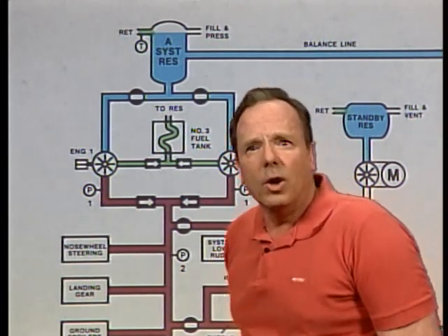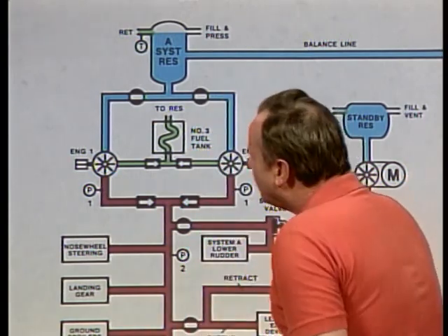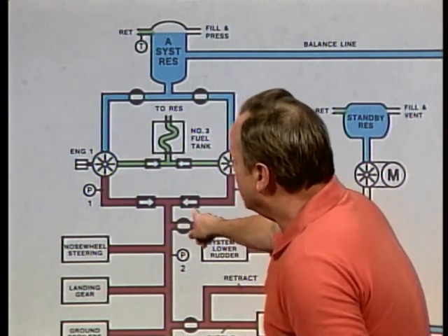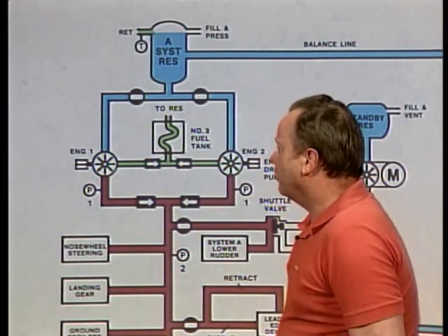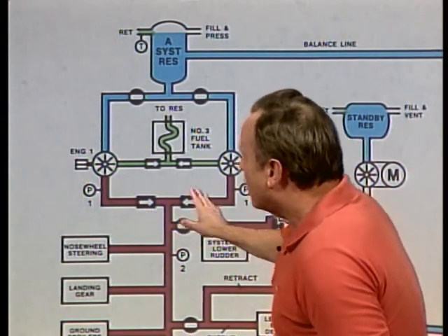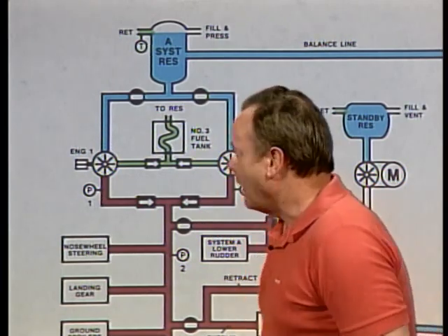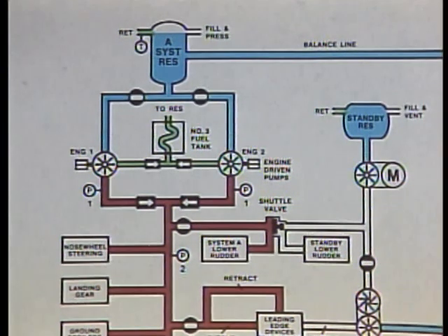Now they're going to ask you, would a hydraulic system schematic diagram indicate the direction of fluid? Well, yeah, that tells you how the system works, so you would indicate that. In this particular case, you see we have these arrows. These arrows represent check valves, but they also show you the direction of the motion of the fluid in the system. So that's part of the functional location of all the parts, and that's what a schematic diagram is all about. So it tells you functional location, not physical location, and it's a wonderful tool for troubleshooting system malfunctions.